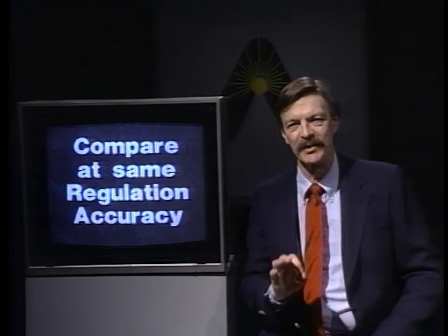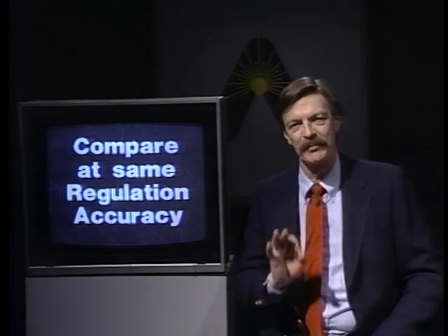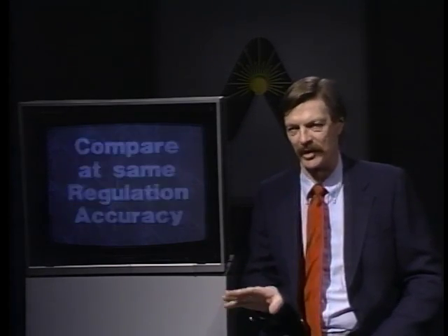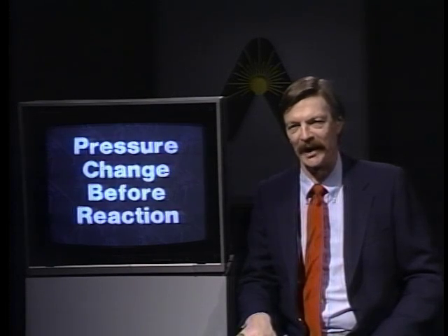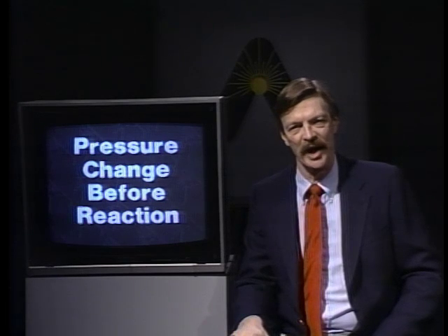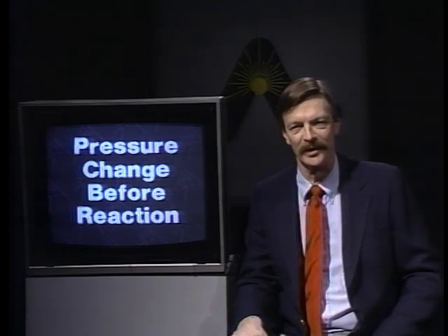When comparing pressure reduction alternatives, it is imperative that the rated capacities are quoted at the same accuracy of regulation, no matter how it is stated. Finally, we define sensitivity as the amount of pressure change that occurs before the valve reacts to control it.